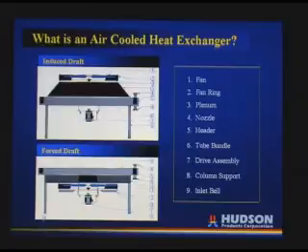Just for information, these can be mounted on the pipe rack at grade. They can be mounted on top of a module, which is typically done for North Slope equipment items, mainly to minimize plot space and to maximize the shipping if you're going to do a sea lift of a full module. There are special applications for North Slope coolers, which we'll cover in just a little bit.